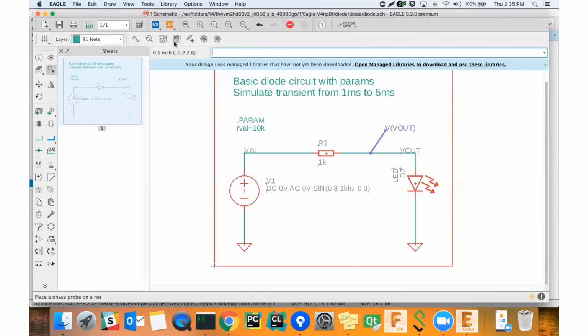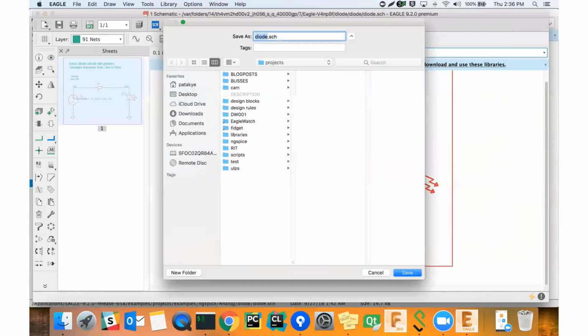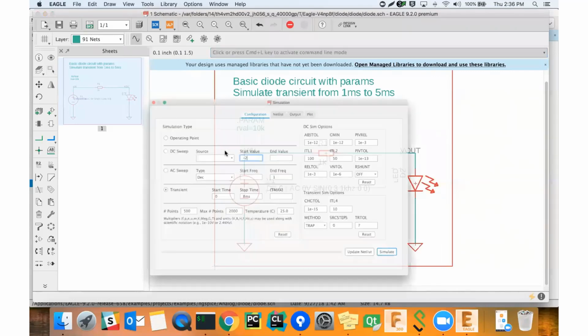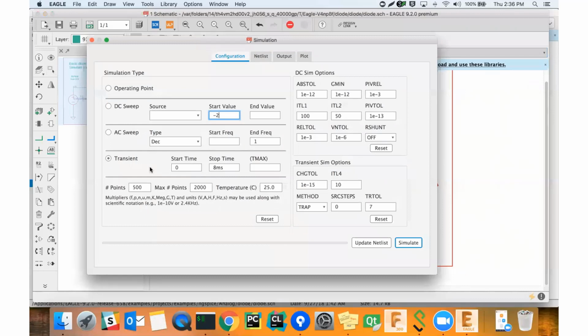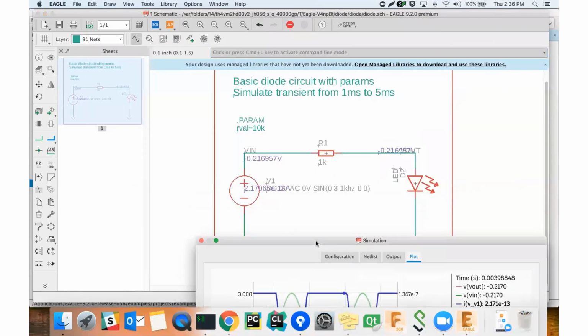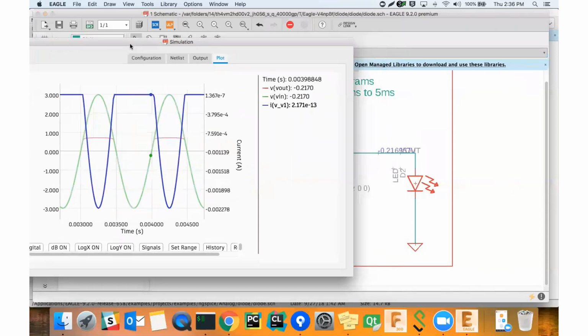There's also another probe type, which is a phase probe. That's useful for an AC simulation over different frequencies, and we'll take a look at that. So deleting my probe, because I do in fact want to see all named nodes in this case, because I did name them and there's only 2. I'm going to run my time simulation again, and I'm just going to point out, for those who recognize this circuit and know what it should do, what's going on here.